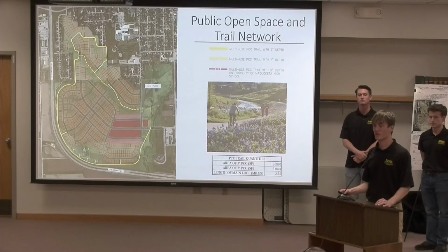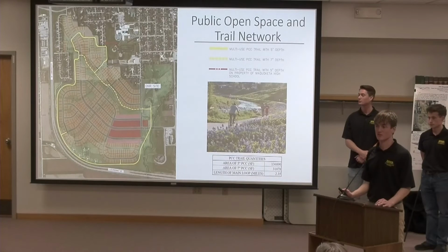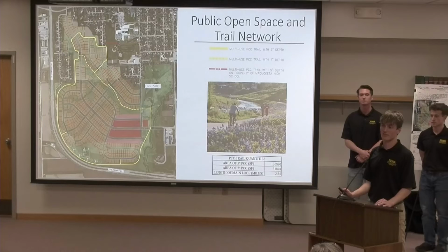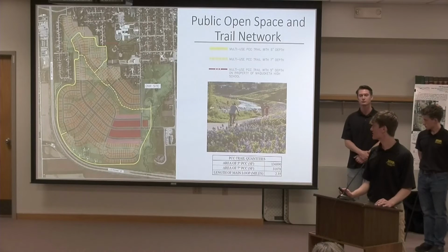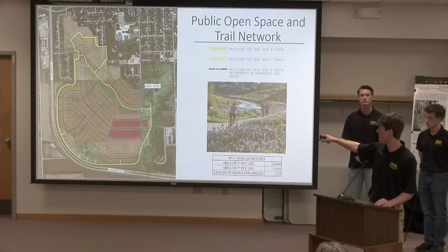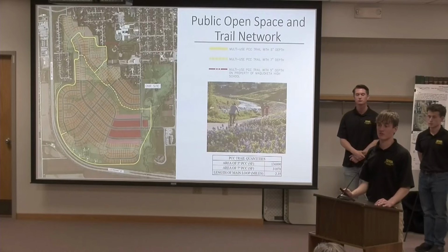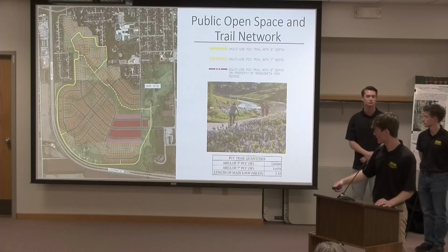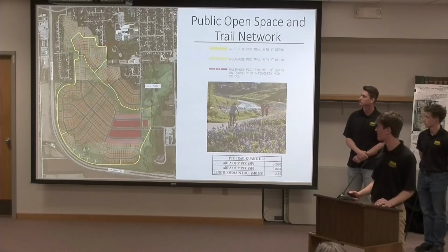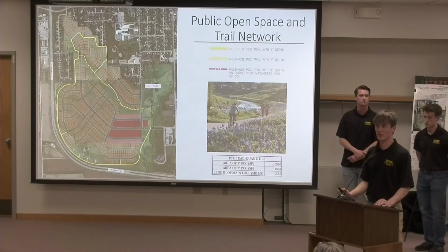That dash portion is going to have a depth of 7 inches, and the reason for that is that the city has sanitary sewer manholes running along there, and so we wanted to provide their service vehicles access to those manholes right there.